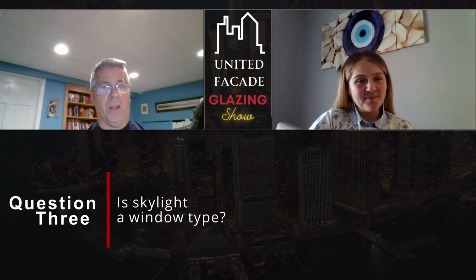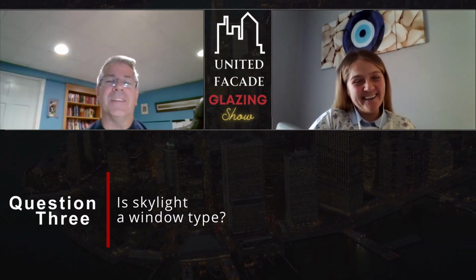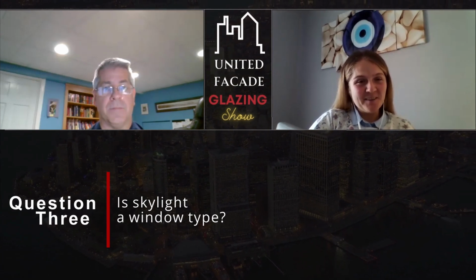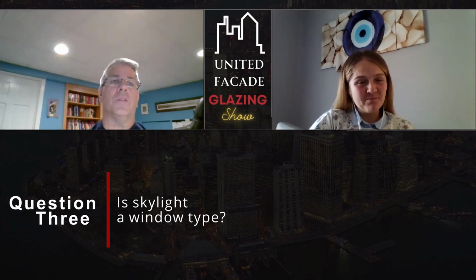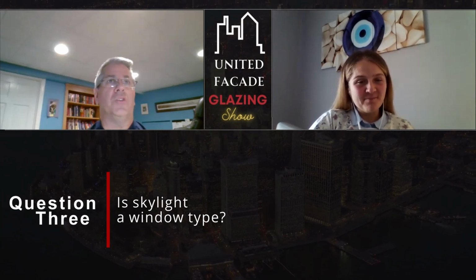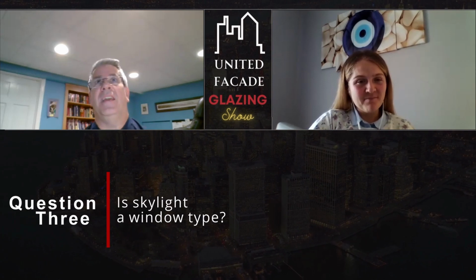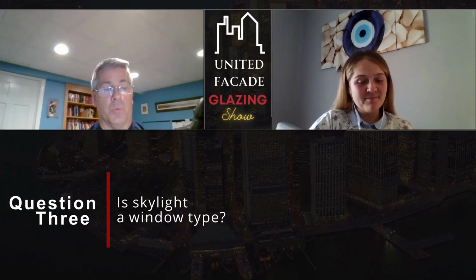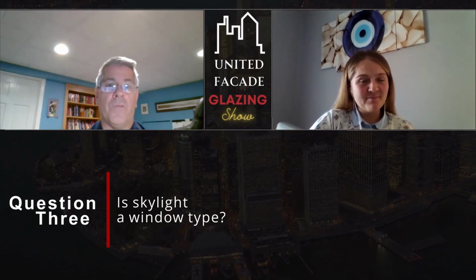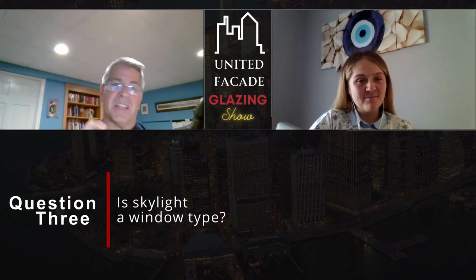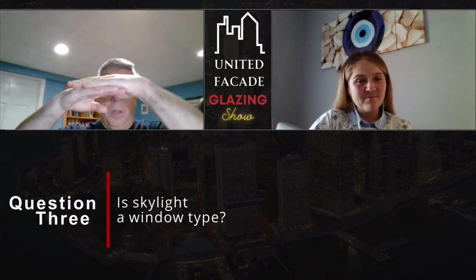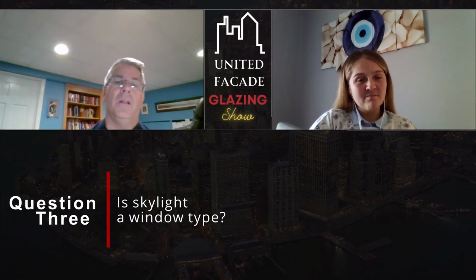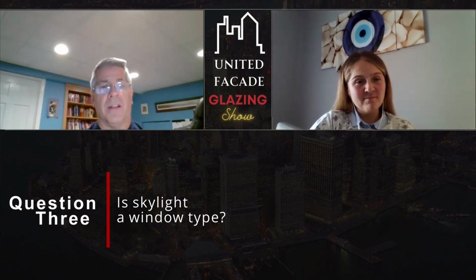Okay, and also now, because you're walking on the glass, a person like you or me say, why would you want to walk on glass? You're going to fall through the glass. Yeah. This glass is very thick. It's going to be, again, a laminated glass. If you think of what's in your windshield of your car, that might be maybe 8 to 10 millimeters thick. This glass that is what we call walkable will probably have 4 or 5 layers of 6 to 8 millimeter glass, all laminated together to make one very thick piece of glass, which is able to withstand the foot traffic of pedestrians walking on top of it above.